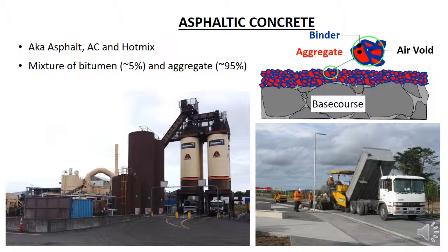The asphaltic concrete can be spread in a thin layer of 25 to 30 millimeters thick to provide waterproofing and a smooth surface, like a chip seal. It is much more expensive than chip seal, but it provides a smoother surface with the resulting reductions in noise and rolling resistance. This can justify its choice for urban areas, where low speeds mean that not as much skid resistance is required and the road noise needs to be kept to a minimum.